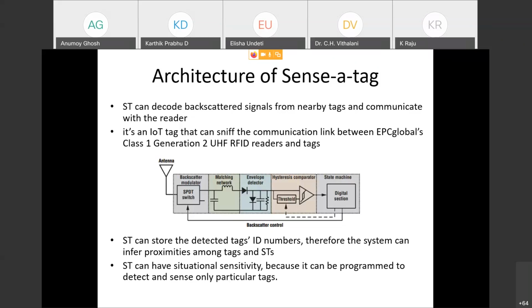Okay, and the tag is connected to the sensor part, and then the sensor will be instructed accordingly. So that is why this digital state machine section is very much important. I cannot directly give out 0 when it is below threshold and 1 when it is just above threshold. Then the tag will not be able to understand what to do. 1 means it is proximal.